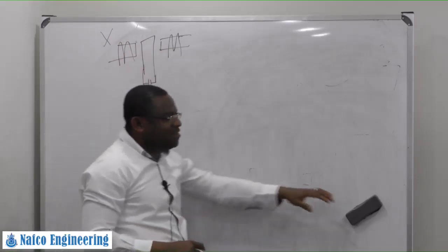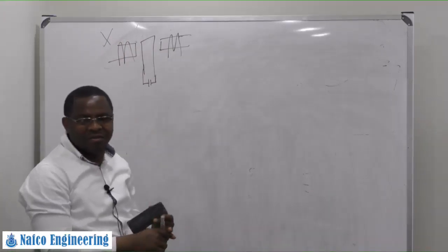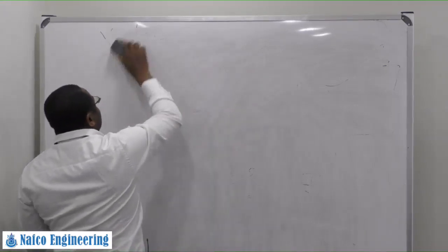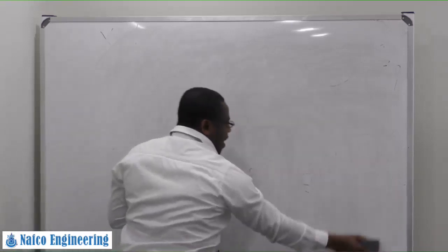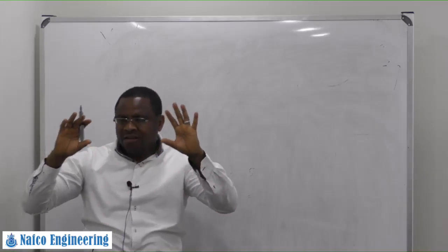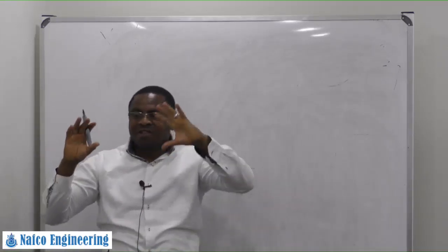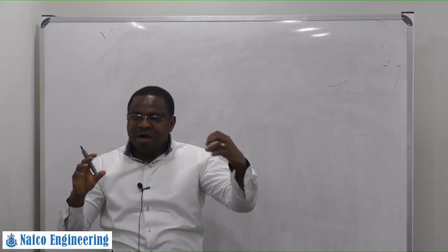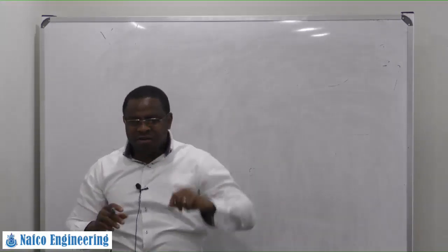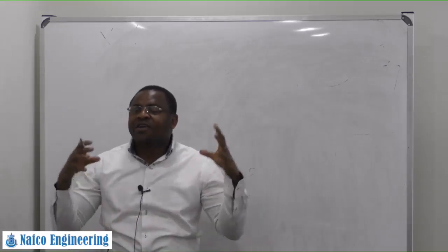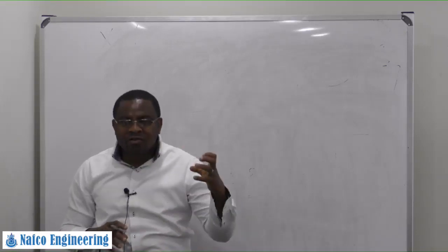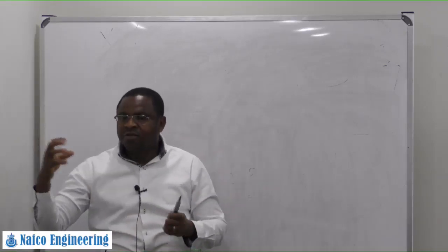We are going to use the same principle of a DC machine for a synchronous machine. For an induction motor, we say it's like a rotating transformer with a rotating secondary. The secondary terminal, we only shorted it. But what we are going to do is we don't have to short it. It must have its own source also, so that we create its own field, and this one will create its own field, and they can lock.